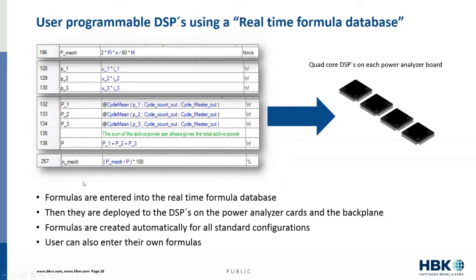Perception creates the basic power formulas and efficiency formulas automatically based on your configuration. And then the user has the option to also create their own formulas. Those formulas are deployed onto the DSPs of each power analyzer board and then calculated in real time.